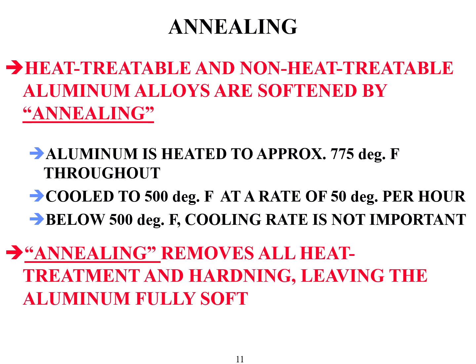We form it. Like I said before, we may throw it back through heat treatment to reestablish a hardness, or sometimes the cold working strengthens it enough in the forming process that it can go as fabricated, which would be a -F designation. Aluminum, in this case, is elevated to approximately 775 degrees, but it's cooled down in stages.